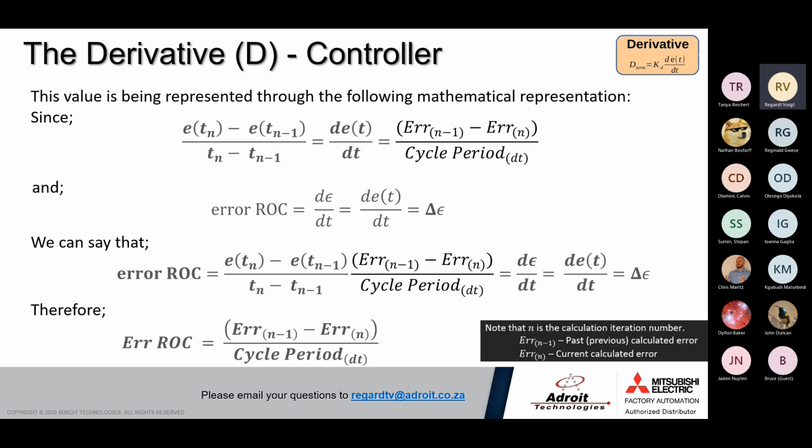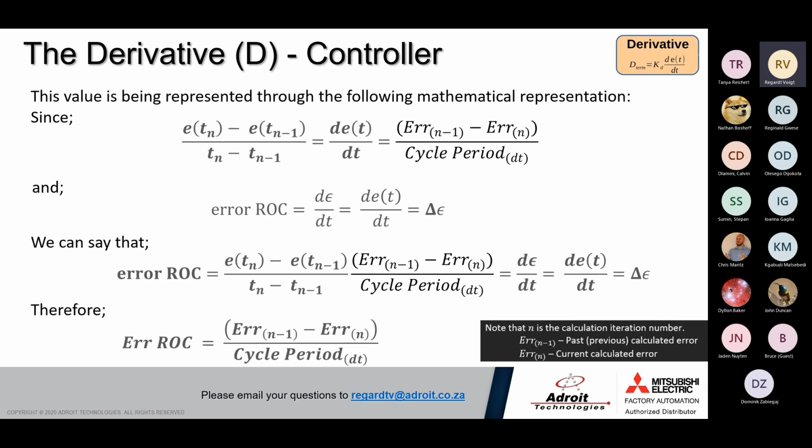I want to point out that these mitigation measures which we discussed now obviously will not address the root cause of the problem, which is noise induction in the cable, which is due to HD cables or incorrect installation practices or unshielded incorrect cables used, or the distance of the cables is too long and so on. So it's recommended that that will be addressed first.